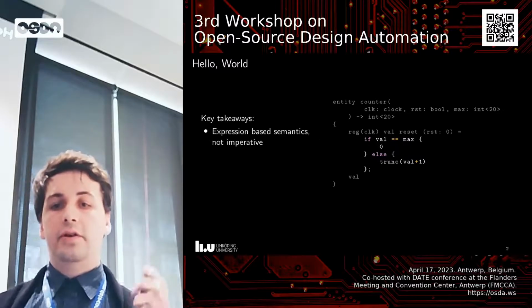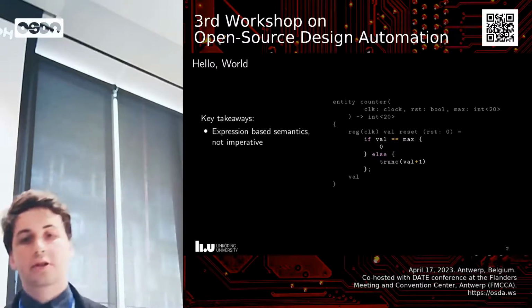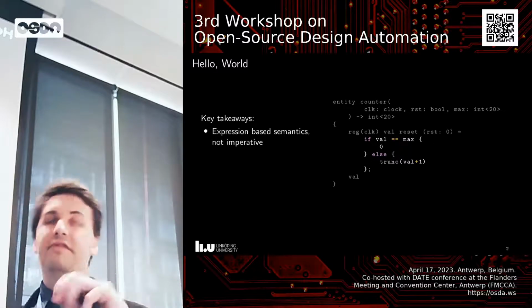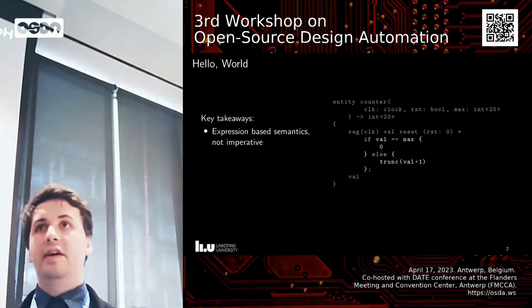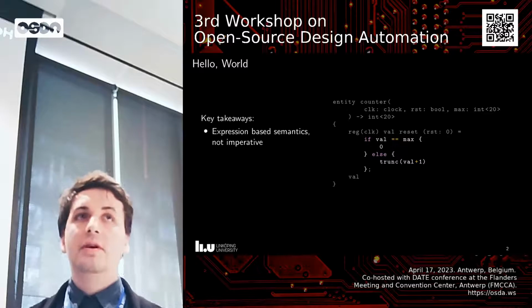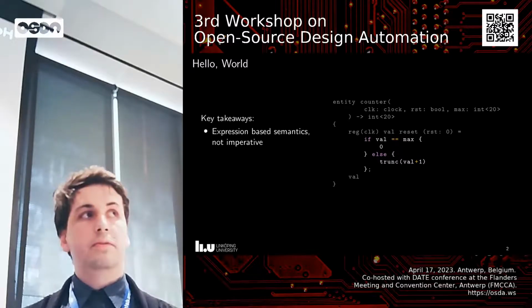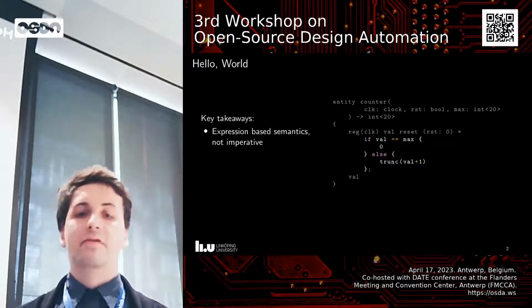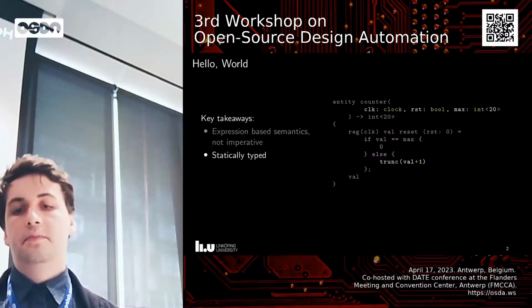Some key takeaways here. First of all, it's an expression-based language. So instead of saying if val is max, set val to 0, we say val is the result of this if statement, and then we have to specify a value in each branch. And that prevents a few bugs, and once you get used to it, I think it's a more natural mapping to hardware than the imperative style that most HDLs have.